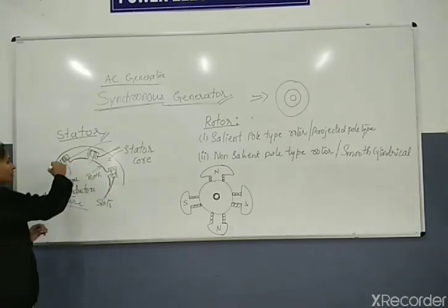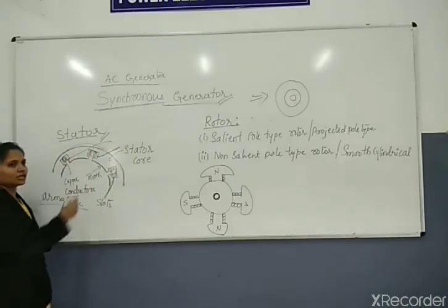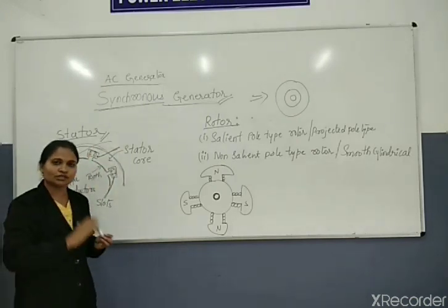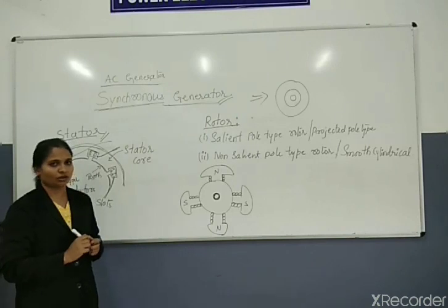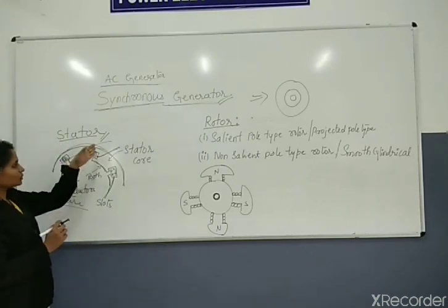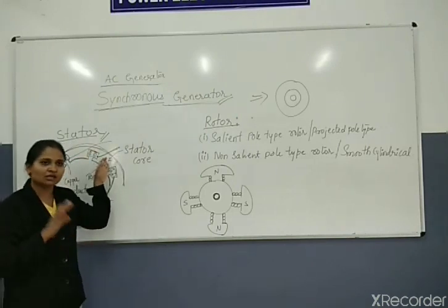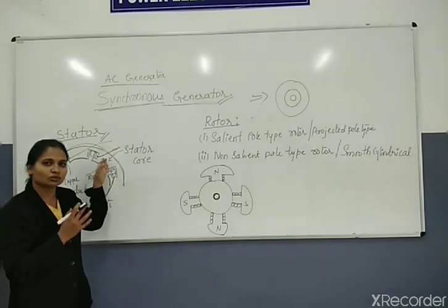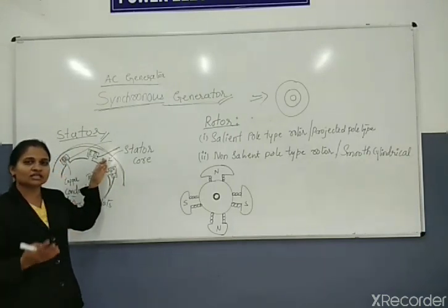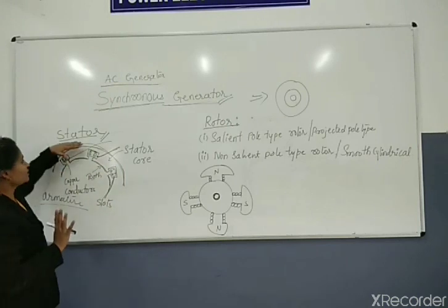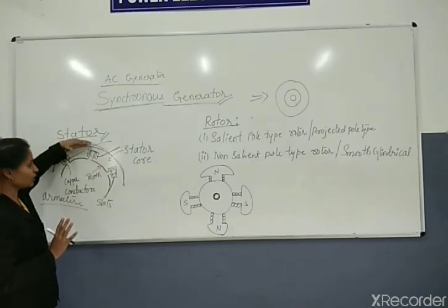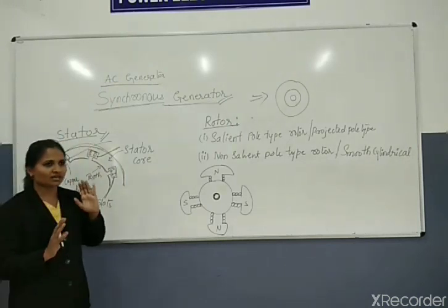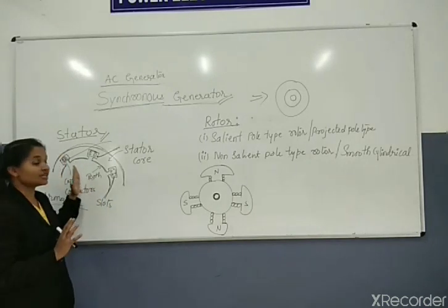Remember, this thin lamination is done to reduce the eddy current losses. The material you are going to use for this is preferably steel, to reduce the hysteresis losses. This is about the stator construction. It is the same as the stator part of a three-phase induction motor.